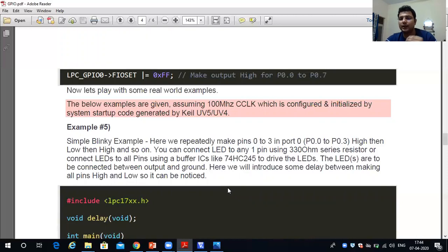So always input and output we have to understand with reference to the system code. So the system is looking for certain input. So that particular pin we have to configure as input pin. The system will write over the pins so that your peripherals can take those outputs as input. Then those pins we have to configure as output pins using FIO direction registers.